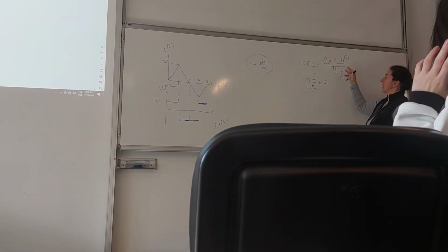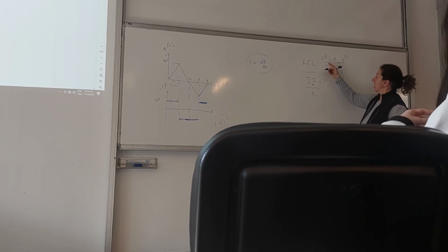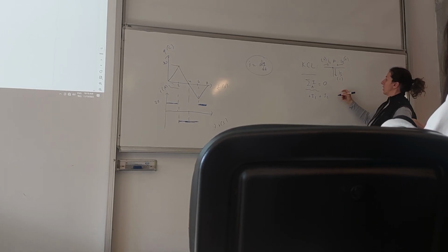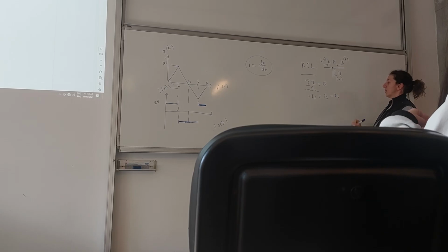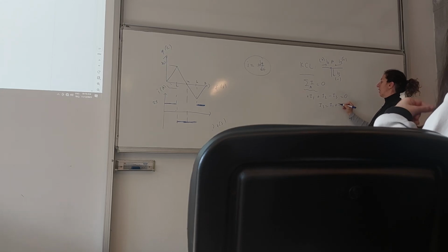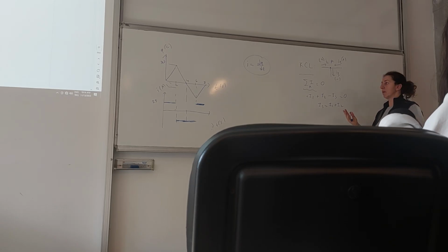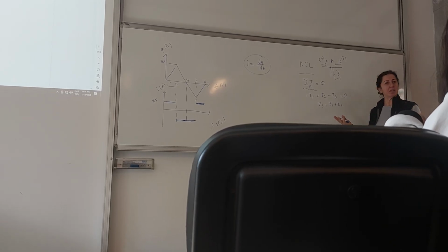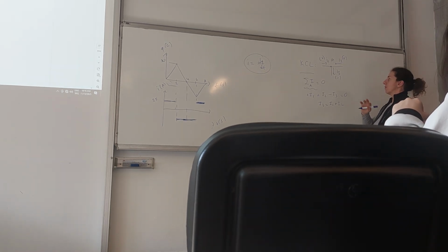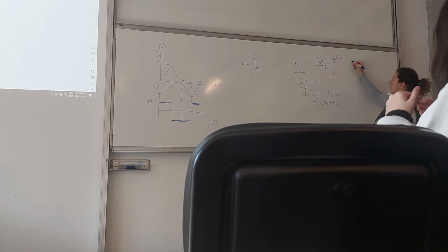So that's why when we put this equation, I1 is entering, so we are adding that. I2 is entering, so we are adding. I3 is leaving, so we are subtracting it. It's 0. That's why I3 is I1 plus I2. Again, when you look at this picture, you realize that it's not a complicated problem. But if there are going to be more than 3 currents, if the directions are going to be all around distributed, make sure that you are writing that KCL correctly.